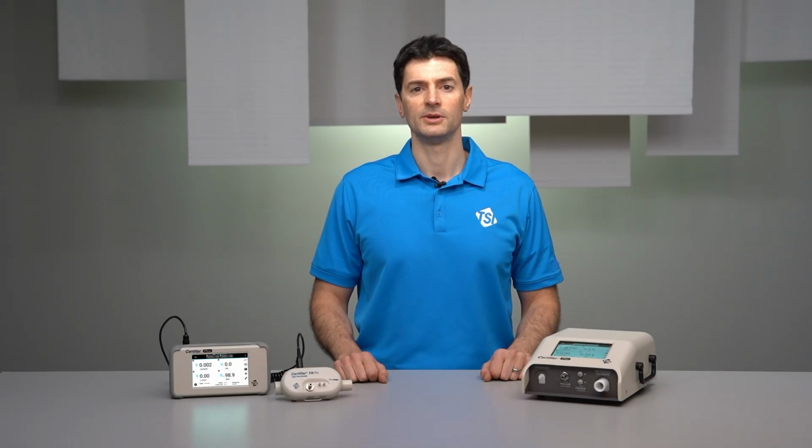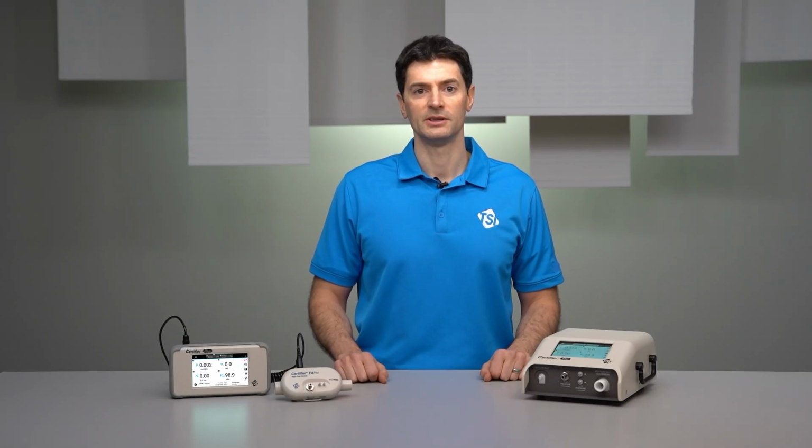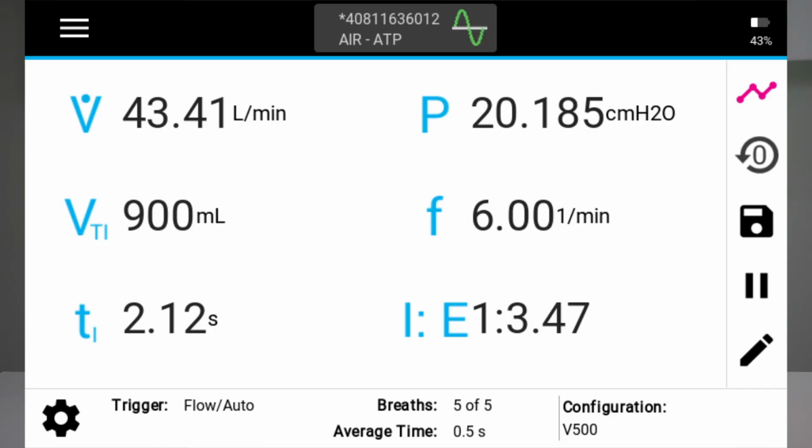These certifiers utilize a touchscreen display which can be operated with your finger or a capacitive touch stylus. The interface has been developed with see-and-touch operation, meaning if you want to adjust a setting, then you just touch on the element that you're seeing in order to change it. The parameter screen is the primary screen used when operating your certifier. This screen displays the measurement parameters and instrument settings, and also provides access to configure the instrument.